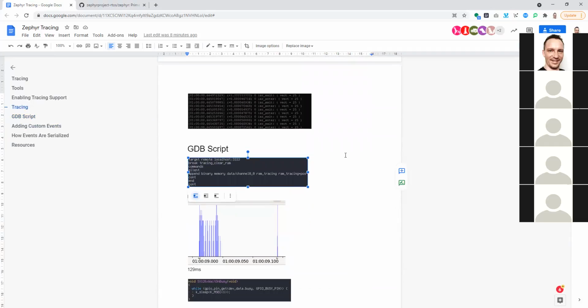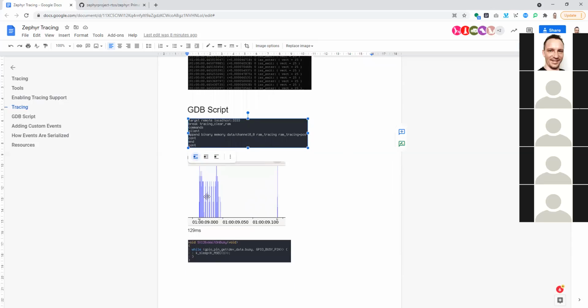So what can we actually get out of this? If you have an application and you need to see what is happening, we can look at this picture here. We have a number of things happening. There are interrupts being triggered in the beginning here. Then we can see from the trace that the application goes to idle mode here, which is correct. It's going to go into idle mode for 1.29 milliseconds.